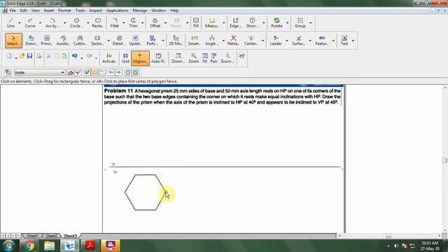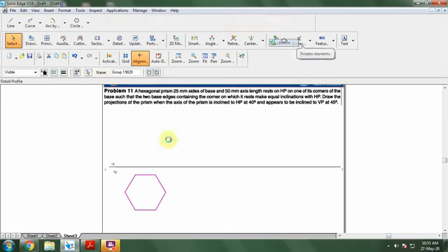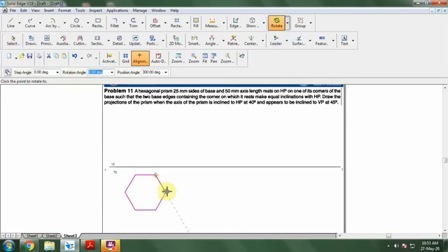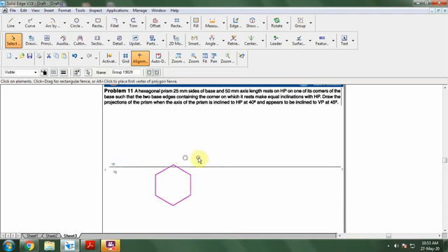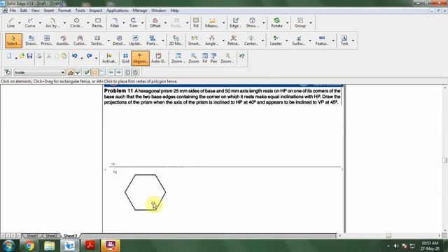So now, since the corner is on the right hand side, I can take this as an initial position because the problem also asks that it is resting on HP on one of its corners. If the edge is resting on HP, I would rotate this for an edge condition like this, so we're keeping one of the edges perpendicular to the XY line. But for this case, it is a corner position, so I'm going to keep it as it is.